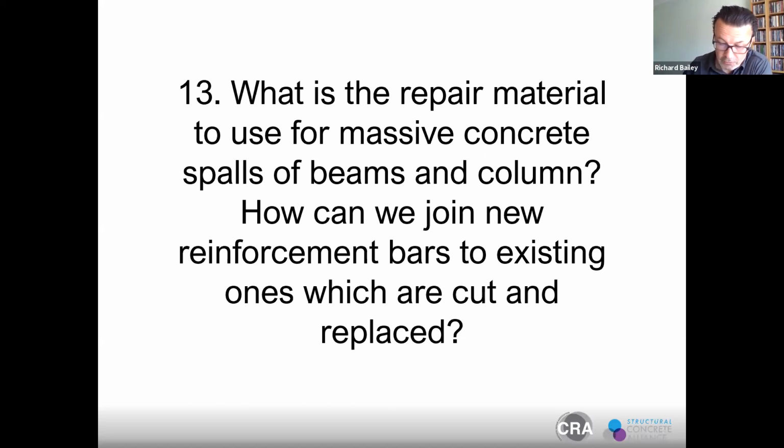The production rate that Paul mentioned for spray concrete is probably relating to wet spray concrete and mass fill. A dry spray concrete will be slightly less production, but it will give you a rapid set, high strength structural repair where that spray concrete can get through the existing rebar. So that's certainly one quick way of mass filling beams and column repairs.